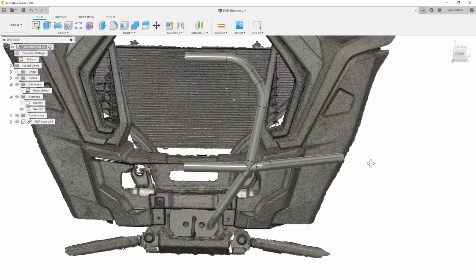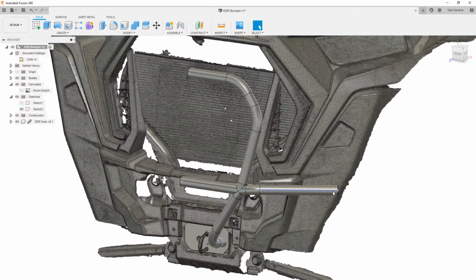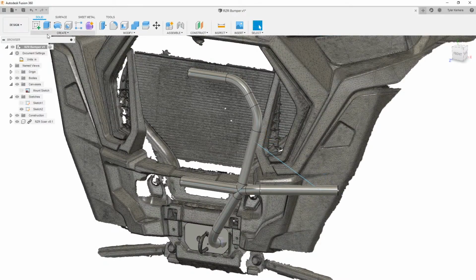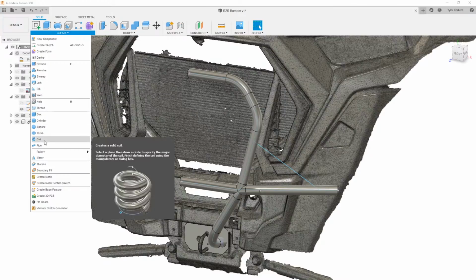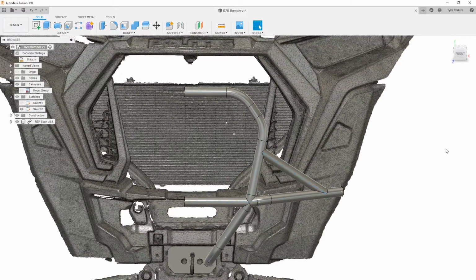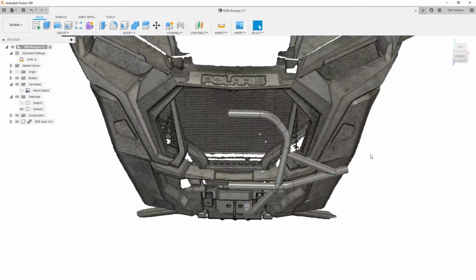So now I think I could probably use a support connecting like this to this corner somewhere in between. I'm going to go back into that sketch again. And this is so easy with 3D sketching. I can just select any point on this line here, any point on this line here, say finish, go through, select my pipe tool again. How easy is that? It just works so nice. And I like that a lot.